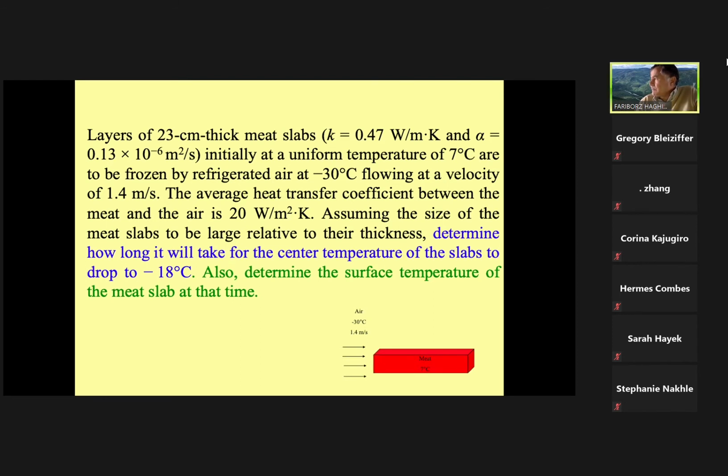Okay. So we have one side from the temperature outside, and then both sides at the bottom, there's the initial. Both sides are the same. We assume this is a meat, both sides are at the same condition. Now, if I remember it correctly, I have two options. The first option is I can use the equation. Remember, if you have your textbook open, around table 4.2 we have a summation from 1 to n terms, and then we have a simplified equation where we only consider the first term.